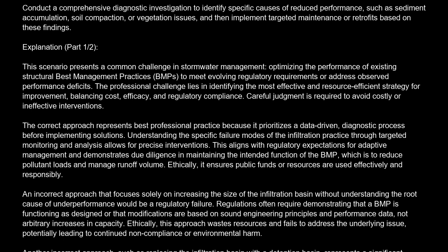An incorrect approach that focuses solely on increasing the size of the infiltration basin without understanding the root cause of underperformance would be a regulatory failure. Regulations often require demonstrating that a BMP is functioning as designed or that modifications are based on sound engineering principles and performance data, not arbitrary increases in capacity. Ethically, this approach wastes resources and fails to address the underlying issue, potentially leading to continued noncompliance or environmental harm.